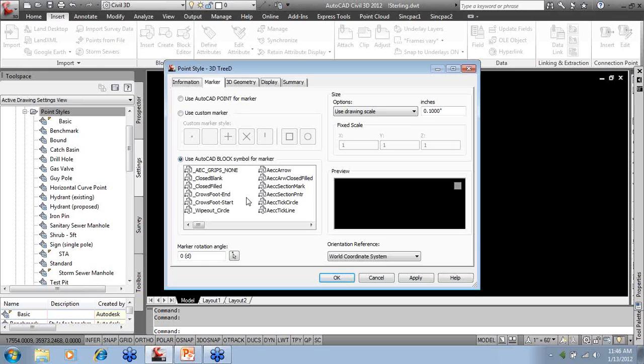You can use Design Center, and you can drag and drop every block individually. Also, how do you get your AutoCAD layers in here? Well, drag and drop your AutoCAD template, go to your Design Center, highlight all of your layers, and drag and drop them right in here into the drawing, and all of your layers would be in this template now. Don't recreate them all.